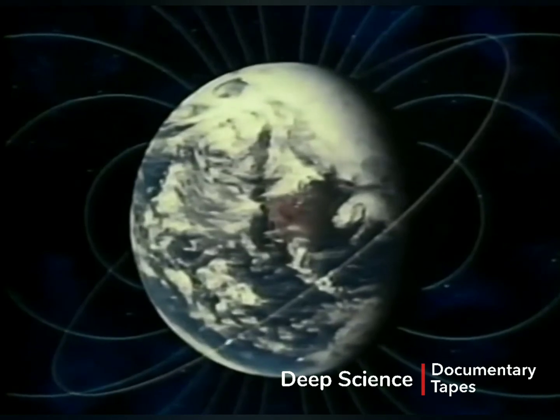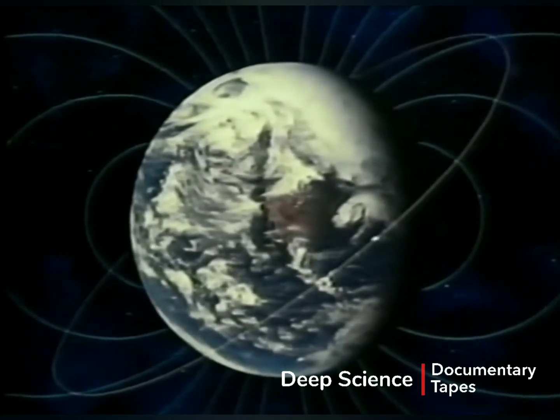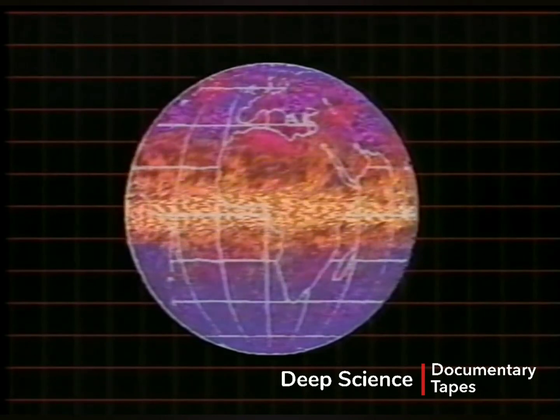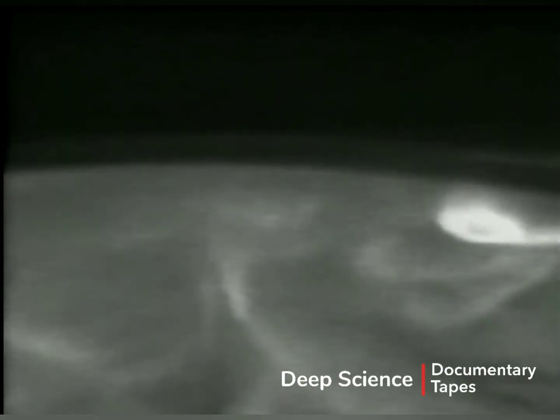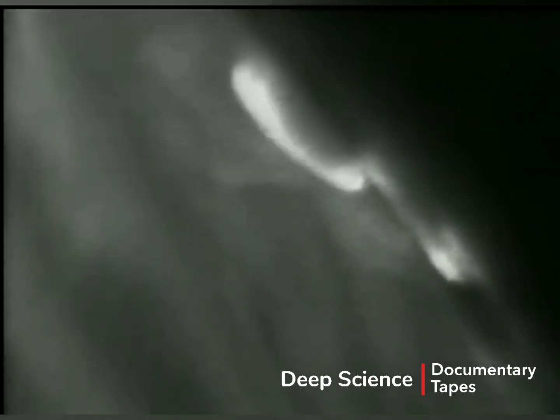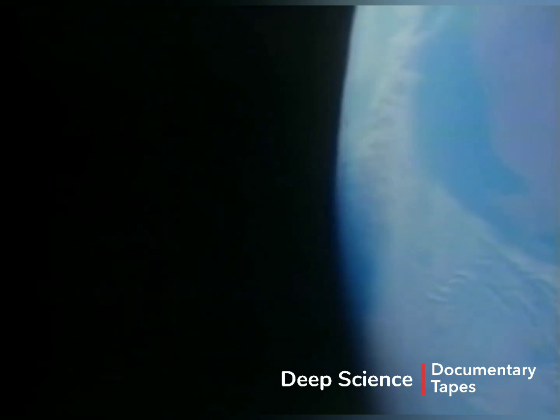The gravitational attraction of the Earth on a spacecraft causes it to move in its orbit around the Earth. There are other much smaller forces which will cause a spacecraft to deviate from its desired orbit. These forces cause what are known as orbital perturbations. Orbital precession, which is used to obtain sun-synchronous orbits, results from the perturbing effects of the Earth's non-spherical shape.